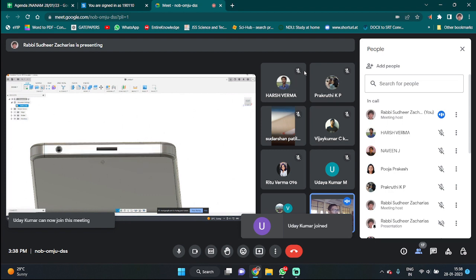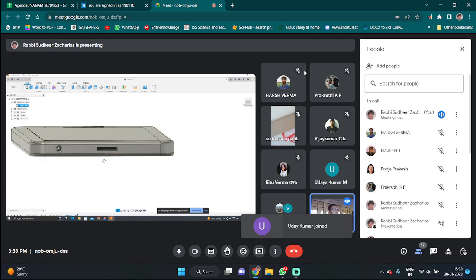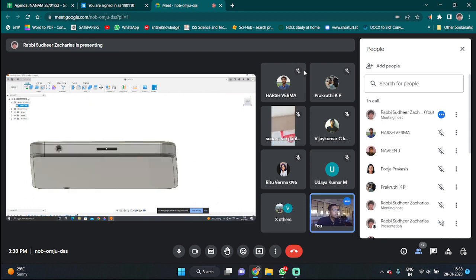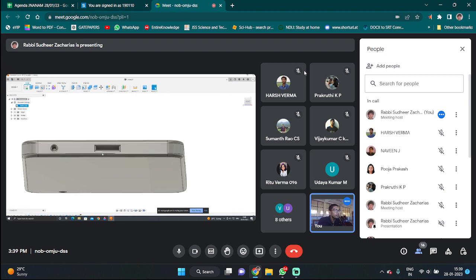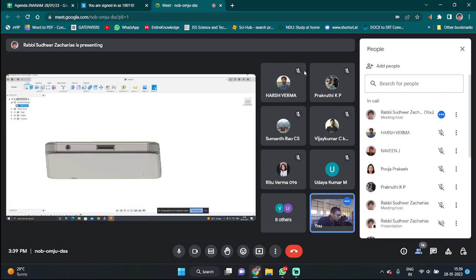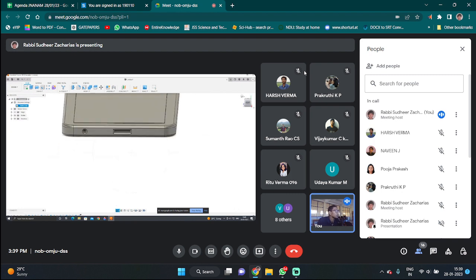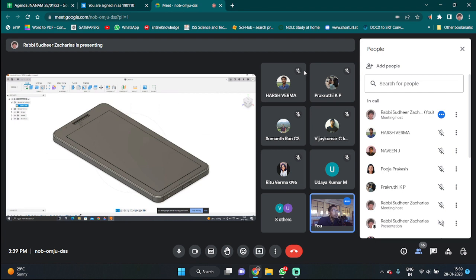A box structure doesn't look right, I mean there are no ports like this. So again, let us smoothen this also. I want to select all the edges. So again, select 1 or 0.5. Okay, fine. This is done. So charging port is done. The jack is done.